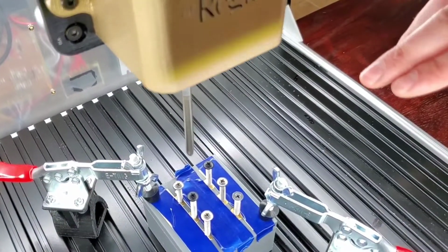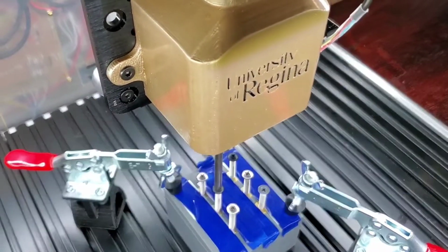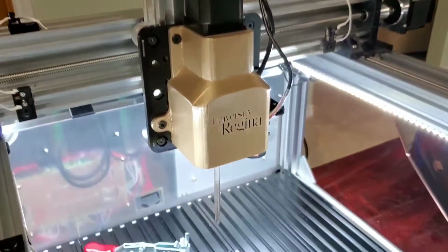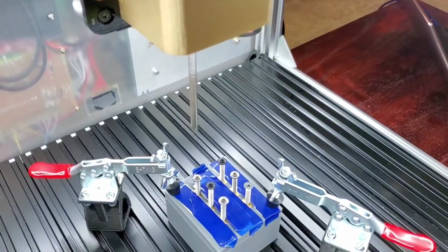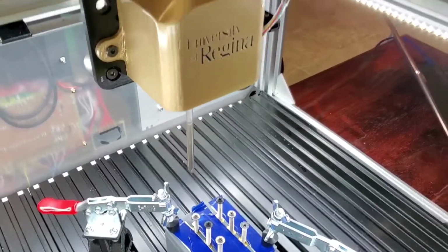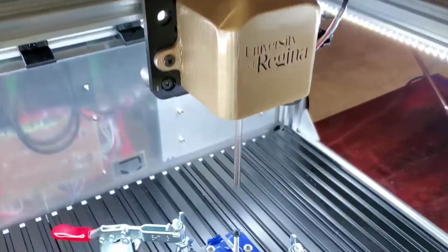So as you can see, it moves down, and just before it reaches the screw, it actually slows down until it contacts this limit switch, and that's how we know that we've aligned with that screw, and we know we've successfully hit it when that limit switch is contacted. Now if that limit switch doesn't get hit in time, then that'll throw an error message indicating that there was no screw.